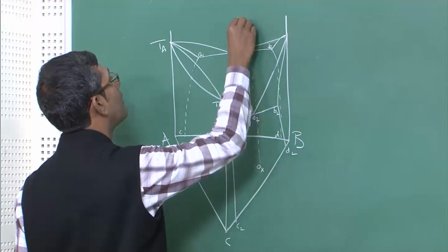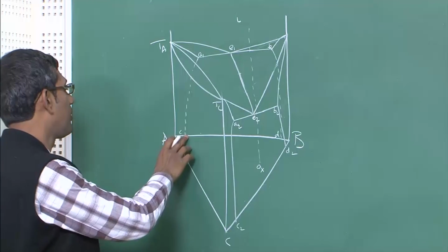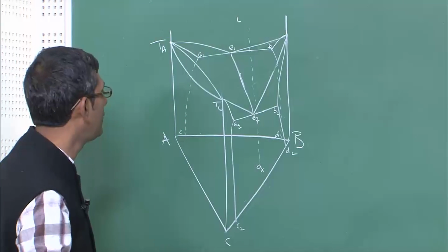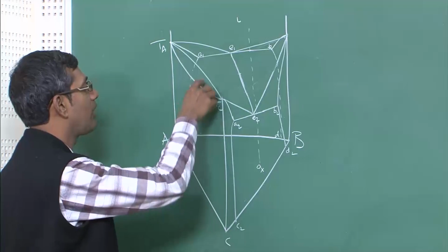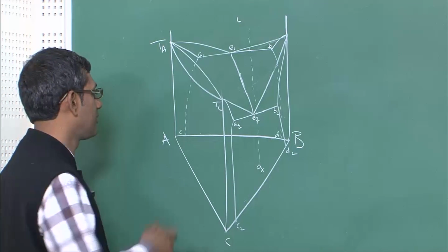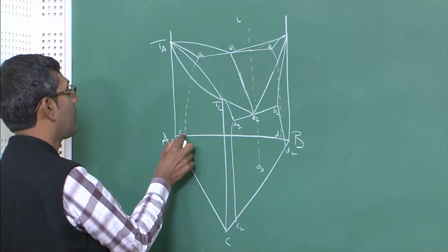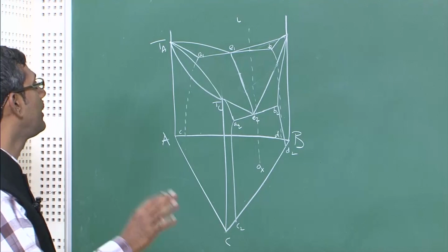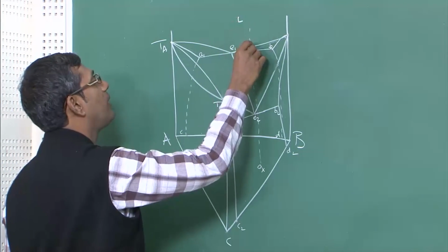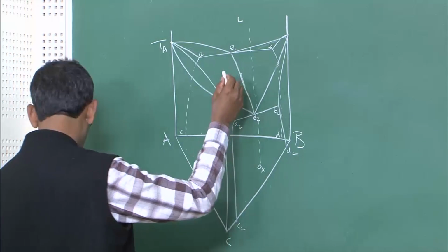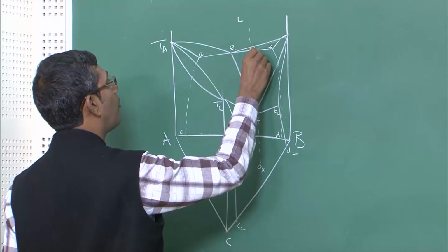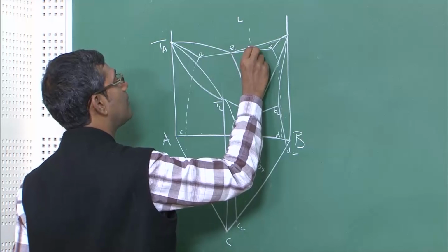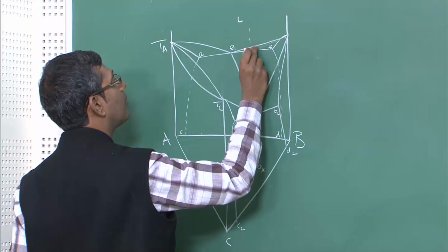First thing is that this is a liquid, as you have seen, this forms a complete liquid altogether above. Complete means miscible liquid, and at lower temperature only this forms solids, with different compositions. Similarly, you can see here the A-rich alpha phase will have this much solute concentration, the B-rich will have this much, the C-rich will have this much concentration. But in liquid it is all miscible together. So, as you cool down the alloy, nothing should happen above point 1. Let me take these colored chalks, that is easier for you to understand. This is point 1.